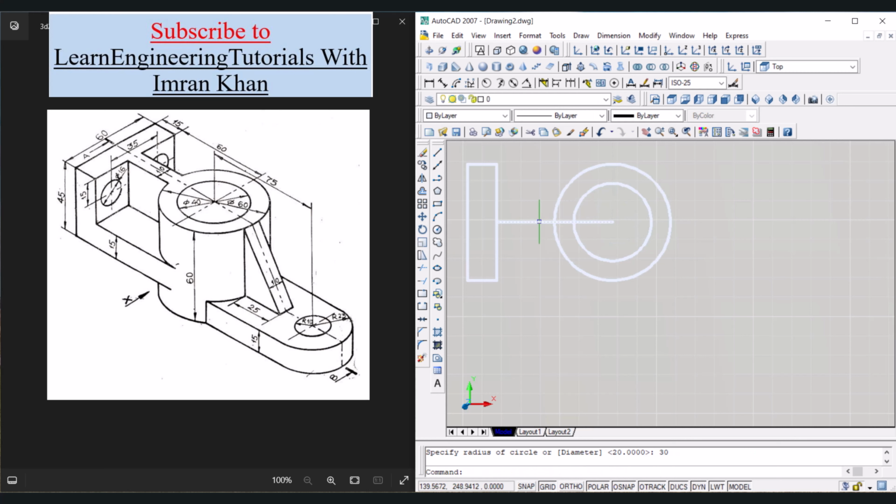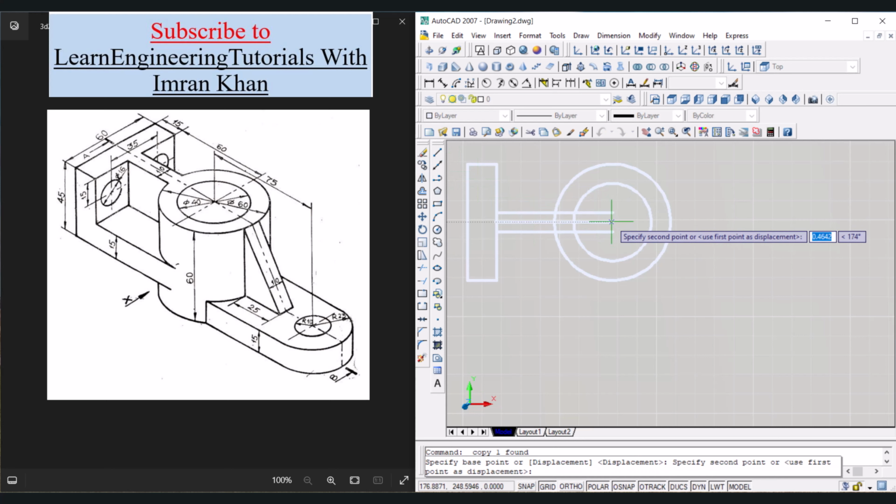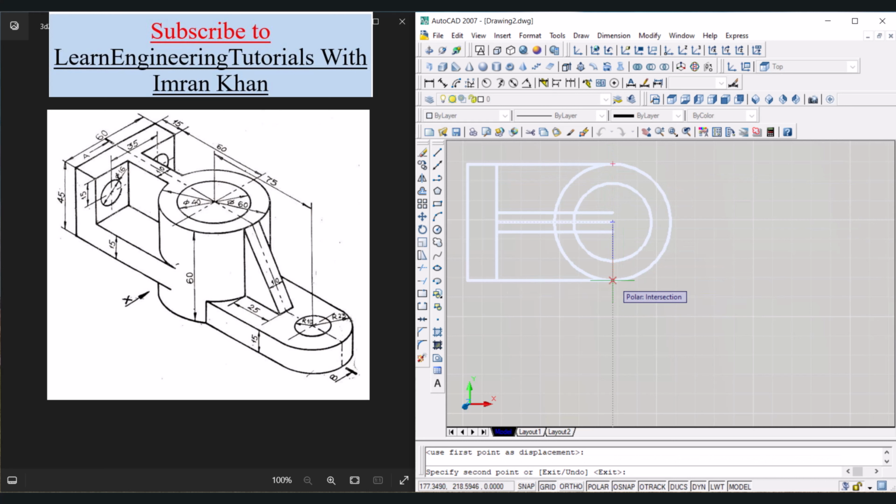Now use offset command, so click on this object, click on offset, the distance should be 5, enter. Click on this side, then click on this same object, click on this below side, press escape. Now click on this middle line, click on copy, select this endpoint, bring the cursor over to this quadrant and this quadrant as well, press escape.